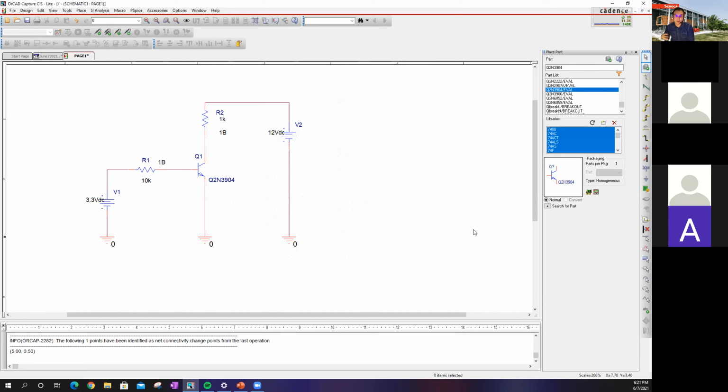So usually when you want to make microcontroller circuits, you want to separate the microcontroller from the larger load circuit, mostly because the microcontroller might not be able to handle the larger current draw, and it might break the circuit. It might break the microcontroller because they're very finicky components, and they cost a lot of money usually. I think a Raspberry Pi costs about $100. Maybe more than 100 as well. When you work in a workplace, they probably have thousands of dollars worth of microchips as well.